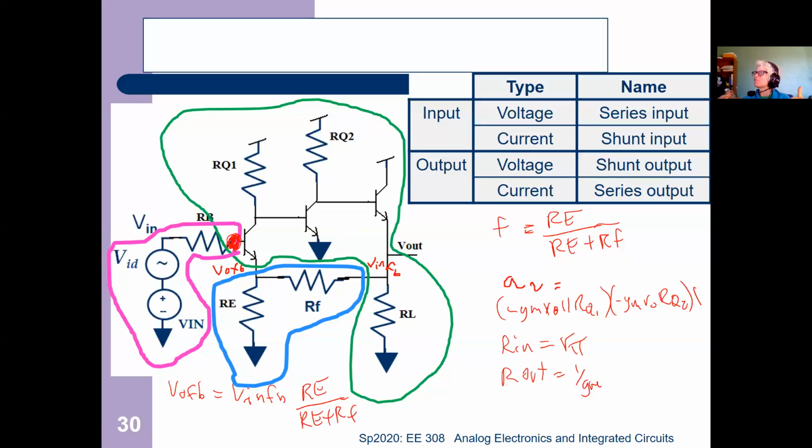So this amplifier, as I have it drawn, is a voltage input, voltage output amplifier. In other words, a voltage amplifier. And this tells you, if the output is voltage and the input is voltage, then on the feedback block, whatever the output of your entire circuit was, which is voltage in this case, the input to your feedback block is voltage also. Confusing enough?